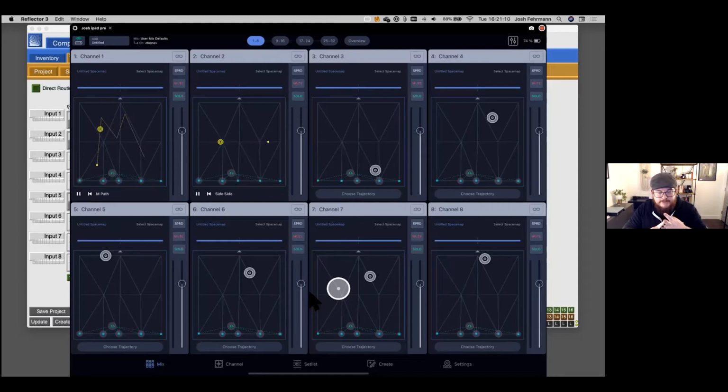With immersive audio, the rules of proper system design change because we've spent decades making mono or stereo systems where one speaker has control of a certain section of audience and another speaker has control of the other, and they meet up right at that 6 dB down point to provide uniform coverage.